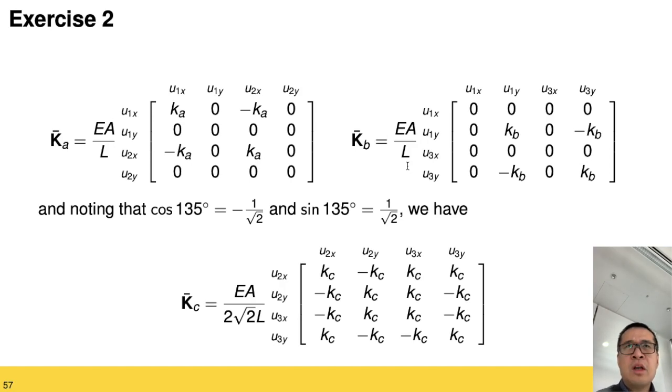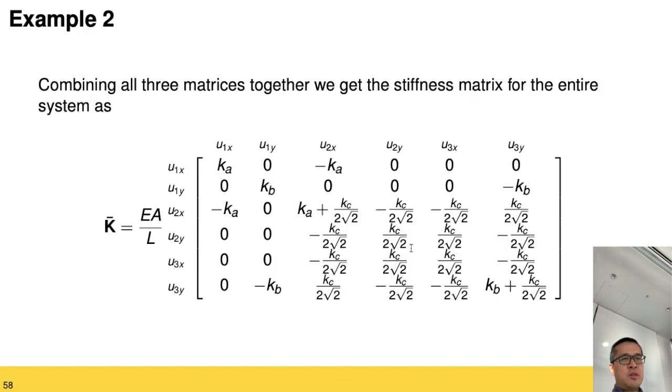So we need to use the trick of zero padding that we learned before, converting each of these matrices into a 6 by 6 matrix by filling up the missing elements with 0, and then you can add them all up element by element to get a final 6x6 matrix, which is shown in these slides here.